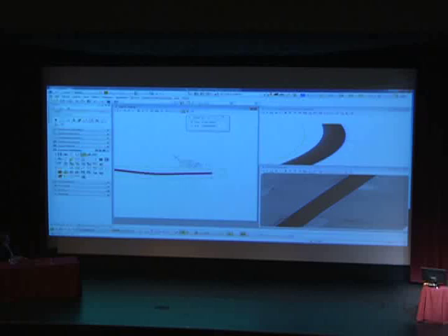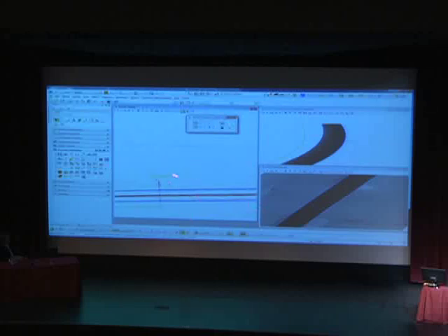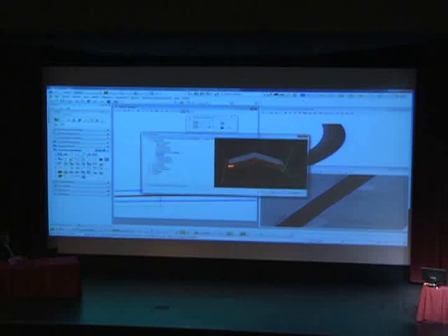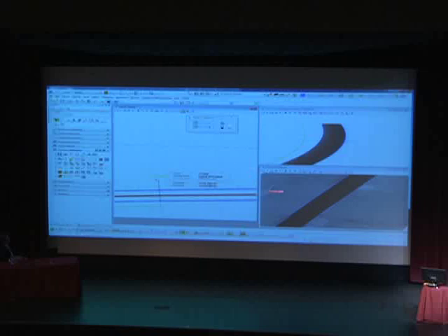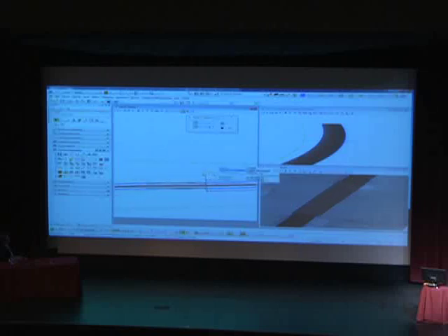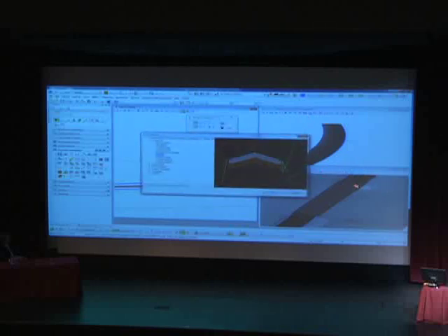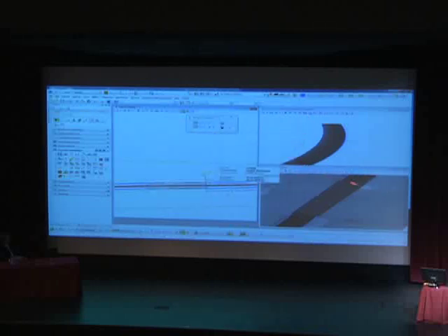Next, I'm going to do a copy template drop. So right here, it's a little difficult to see, but this is supposed to be a bridge section actually, and it's not represented very well. So I'm breaking my corridor, and I'm placing a new template in between these. It's still a solid corridor, but there's a different template between the two. I'm going to the properties, and I'm just going to select the bridge template. And now this place automatically updates to the new bridge template. And on this edge over here, I do not have a ditch bottom. It's just slopes. So I'm going to switch this template to have slopes. Now the slopes are not connecting to the terrain.